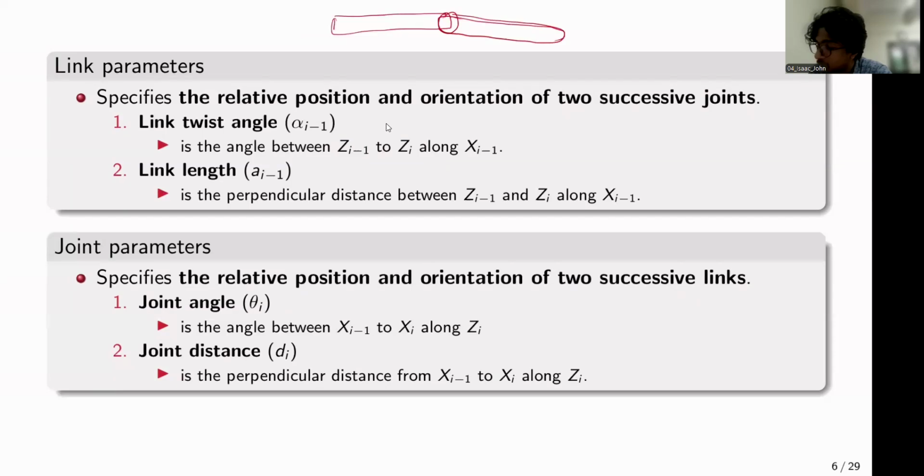So the first joint, the joint associated with the first rigid body, I label this as rigid body 1 and this to be rigid body 2. So the joint associated with the first rigid body is vertically upward, something like this. I hope this is clear. So I label the direction of the joint using the z-axis. So I label this as Z1.